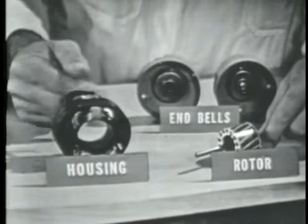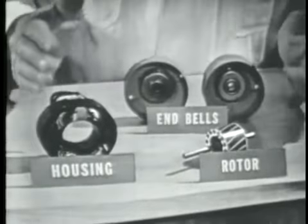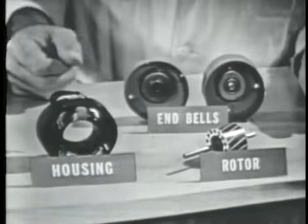Right. Now, there are no slip rings or wire windings. And, of course, overall construction is very simple, very rugged. Okay, item 2. Very good. I'll take this one. The basic principle of operation of the AC induction motor is conductors placed in a rotating magnetic field will become magnetized, and if allowed to rotate, will follow the moving magnetic field, as the rotor is doing in this case. Right.